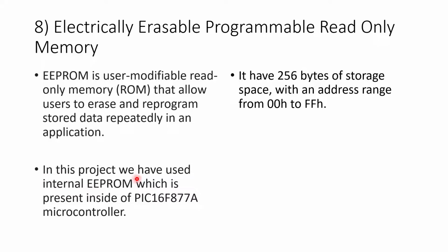In this project, we have used internal EEPROM, which is present inside our microcontroller. The size of the internal EEPROM is 256 bytes. The address range is hexadecimal value 00 to FF.